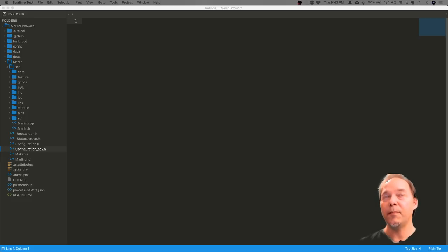But if you do find that STM32, or any other HAL, is having trouble with U8glib, we have U8glib-HAL, our own copy of it inside the Marlin firmware project, so we're actually able to update it and make tweaks, and they'll roll out, and it'll be built the next time you bring in that version of the library. But it's a good idea, I think, in general, to just make sure you have the latest version of U8glib-HAL. Platform.io will get it for you automatically, and as far as actually building for AVR, it probably doesn't matter. You can just use whatever U8glib you have, and it'll be fine. The HAL version is mainly to be able to support the other 32-bit platforms and make them work well.